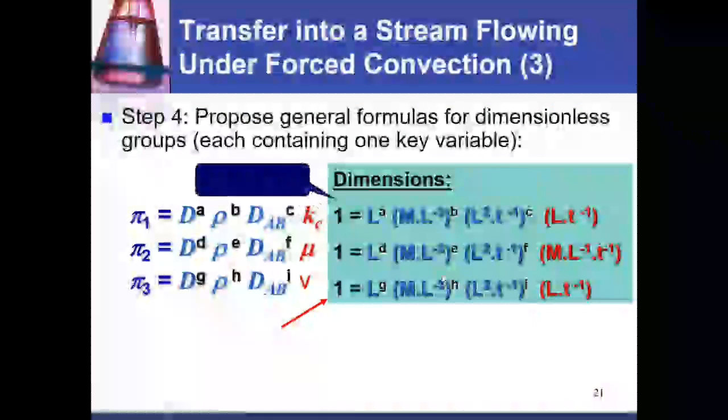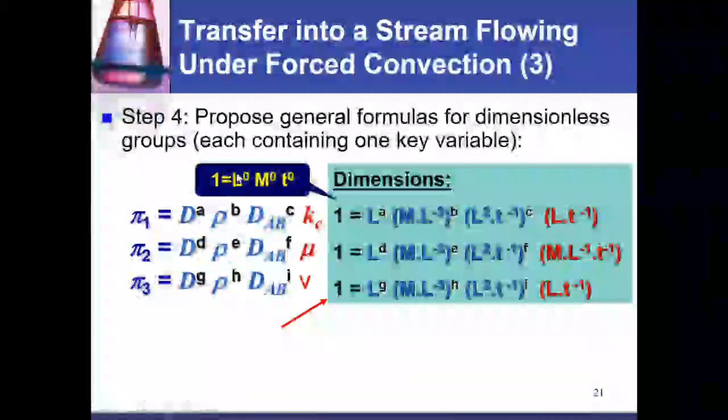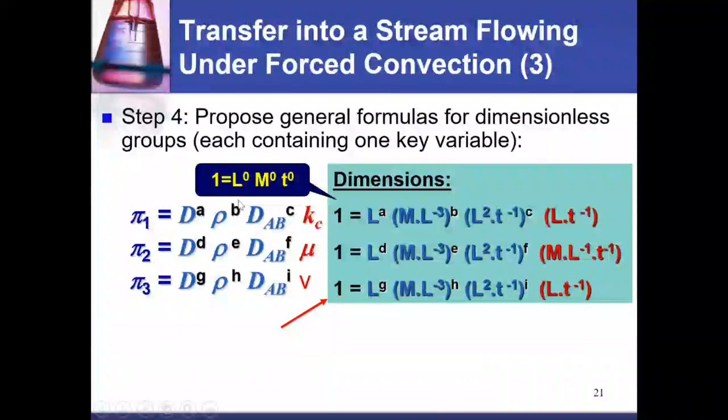And H1 should be raised to the power 0, because when you raise anything to the power 0, what do you get? 1. So this will be 1 times 1 times 1. So it's dimensionless. And the summation of these powers for L should be 0, because the left hand side and right hand side should be equal.